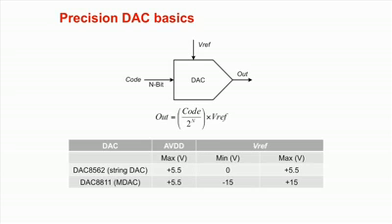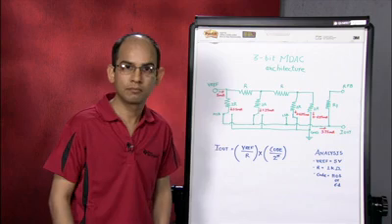The second differentiating feature of an MDAC is the output pin. While most DACs provide a voltage output which is either buffered or unbuffered, the MDAC provides a current output. So, you need an external op amp to convert this current into a voltage output. For simplicity, I will walk you through an example of a 3-bit MDAC.